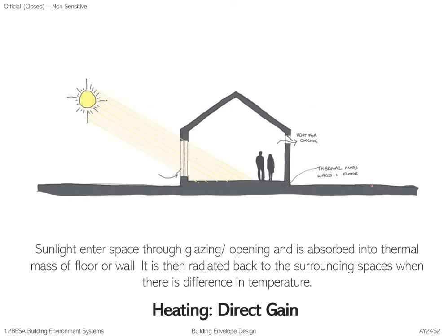In this case, once again, you're collecting as much winter sun as possible. So what are you going to design? How are you going to design thermal mass? I know that for the floor, I will probably want it to be rather heat absorbent, because I want to collect the sun to warm the night time. And for the wall, there would be a difference between the wall at the opening side, because I want to maximize the fenestration, the opening, as I want as much sunlight to enter as possible, whereas on the other side, the thermal mass for the wall I would also want to be rather thick, because I want it to be well insulated from the cold outside.